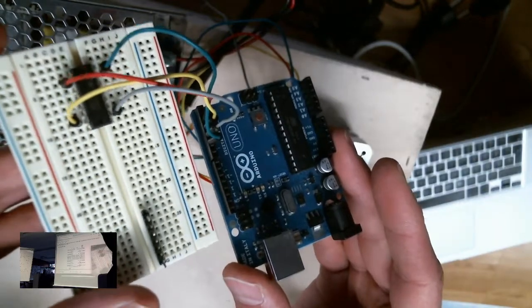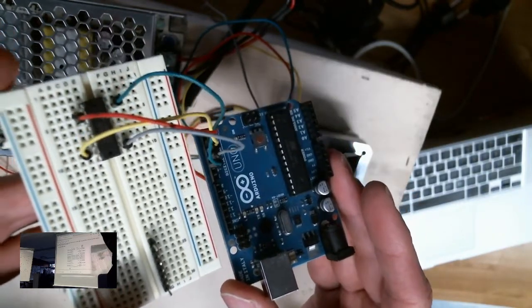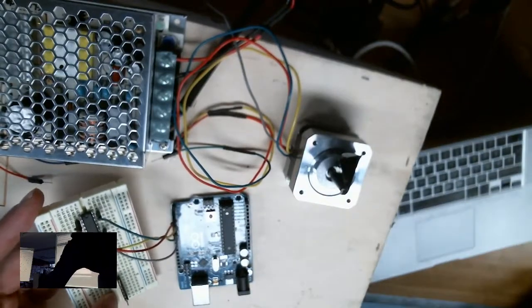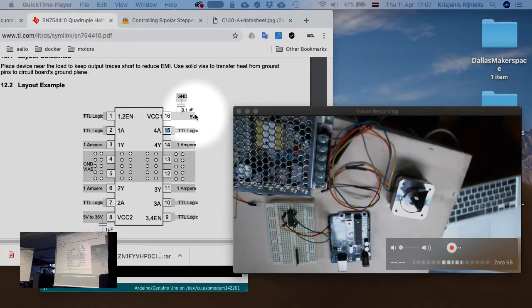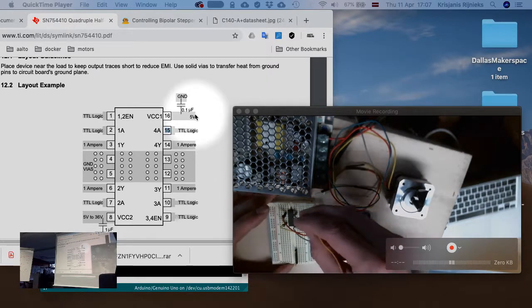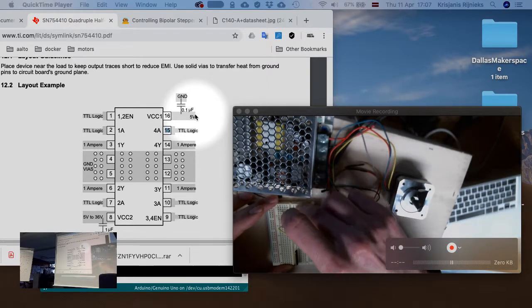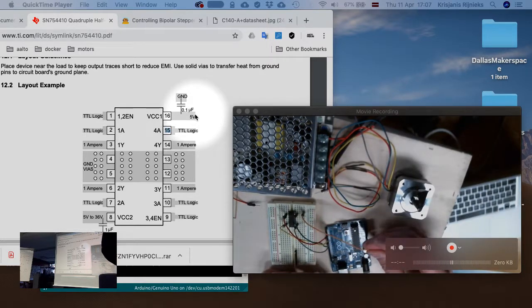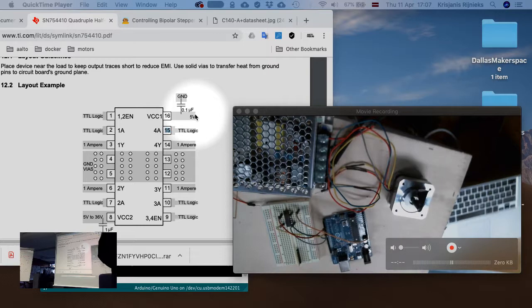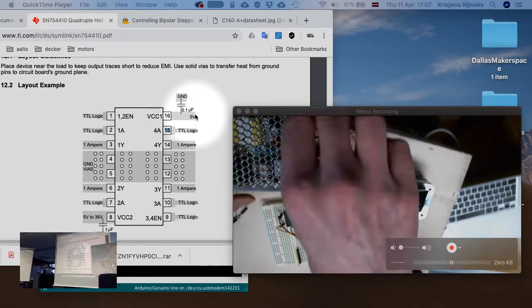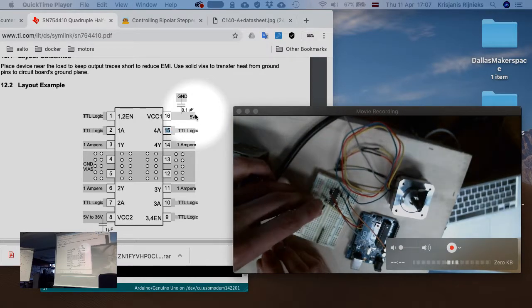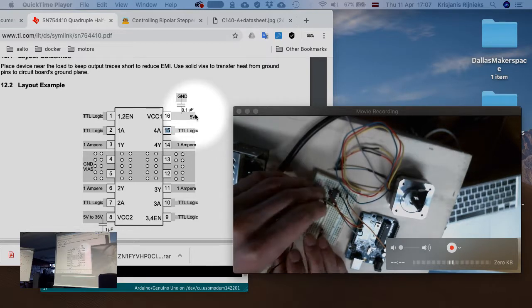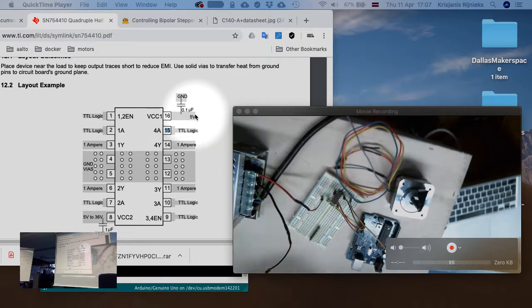And yeah, the top right we need to connect. So I'll switch back to the view over here. The top right should be connected to 5 volts from the Arduino. For that I'm going to use an orange cable just to make it different. So here, top left, plus 5 volts from the Arduino, and the power supply over here. We are going to connect the plus 5 volts of the power supply to the bottom left. I'm going to leave some distance so we can see what cables go where.